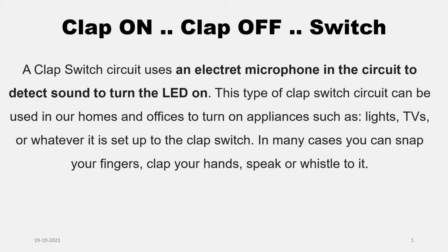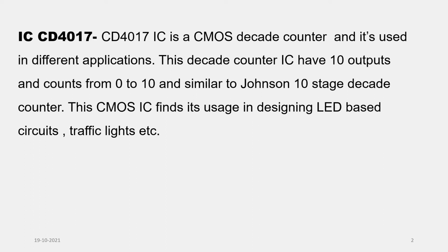Our voice, claps, and finger taps have varying frequencies. When you clap your hands together, the frequency ranges between 2200 Hz, as I've read, to 2800 Hz. So if the Electret microphone can pick up the sound, then you are good to go.